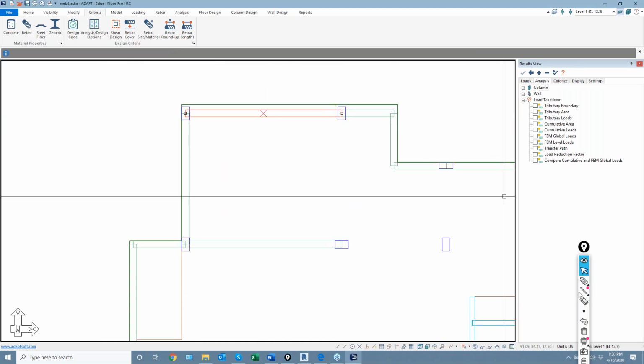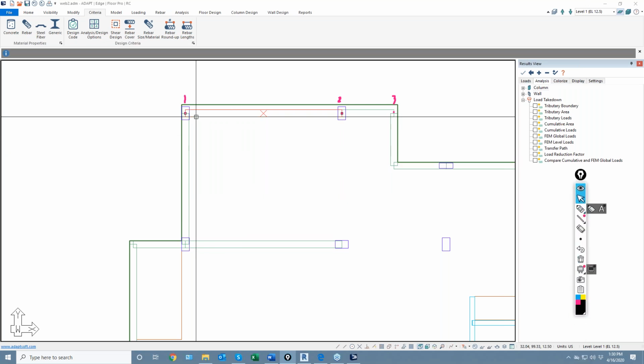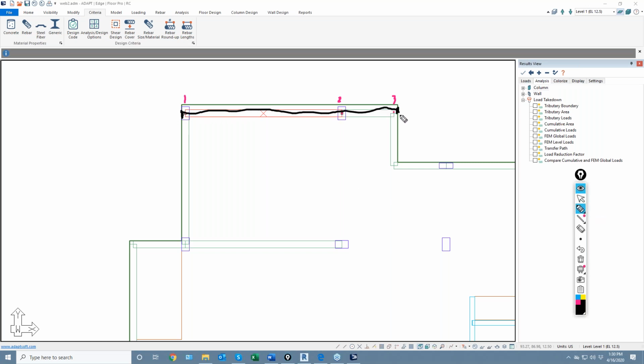You'll notice this beam is broken up into, I'll call it, 1, 2, and 3 nodes. There's a node here, a node there, and a node here. So if you add a support line along this beam path, I'll color this in black here. If I say, well, my support line is going to go from here all the way over to there, and notice I've skipped snapping on points 1, 2, or 3.